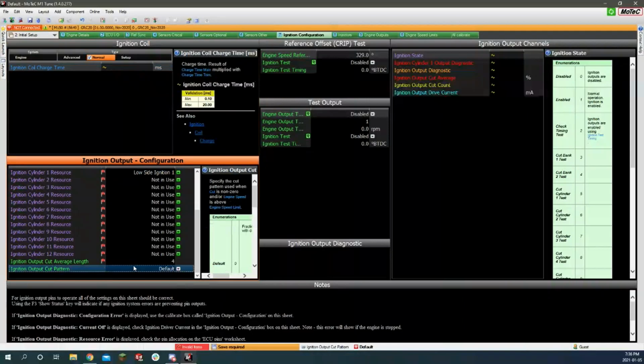This is often done with two-step. If you hear a car with really noisy two-step, shooting fire and stuff, most drag cars will do this to build up boost on the line. They spin up their turbo. It's really good at that. The problem is it's super hard on engines. Some engines are not built for it.